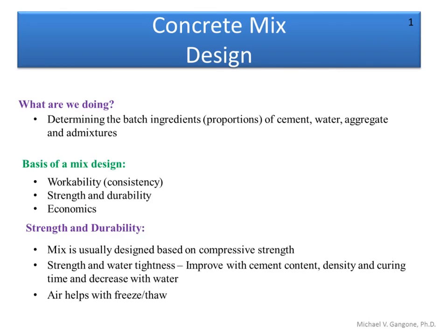But again, air entrainment is an admixture. It's a chemical admixture that's put in the concrete to create these little air bubbles, little air voids. And again, remember what is happening there. It creates a space for water to expand when it freezes. All right, so that really does help keep the concrete more sound, so to say, and reduces some of the cracking, and it reduces some of the spalling effects that might occur from that water freezing and pushing against aggregate and other things like that in the concrete and causing parts of it to break.